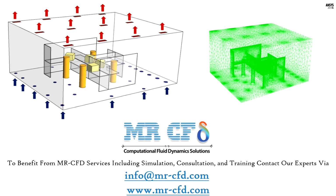The present model is designed in 3 dimensions using Design Modeler software. The geometry of the model includes an office desk in which 4 computer cases and 4 simulators are located as heat sources. There are also sections as air inlets and outlets on the floor and ceiling of the office. Also, the meshing of the model has been done using ANSYS meshing software, and the mesh type is unstructured.